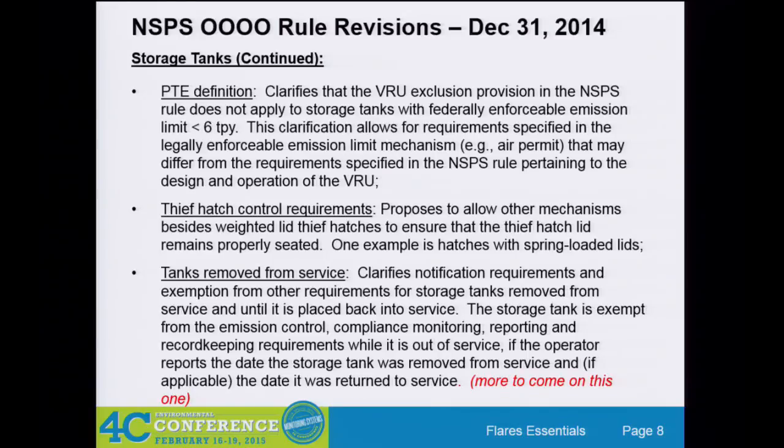Thief hatch requirements, one of the banes of the industry. That's basically a gauging hatch on top of the storage tank. They either get left open by your water hauler, oil hauler, or they're not well maintained. And so there are requirements around thief hatches, mainly to just say, hey, there's other mechanisms that you can have in thief hatches to keep it properly seated, and the EPA didn't want to be quite so restrictive.